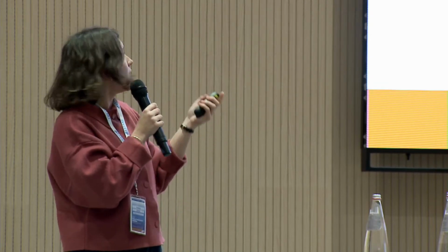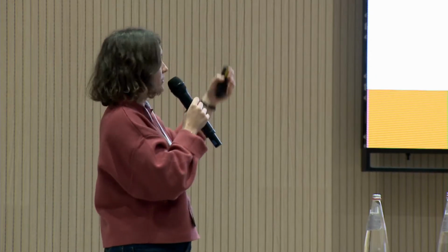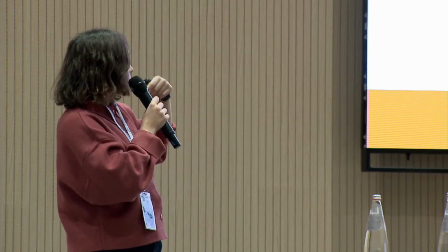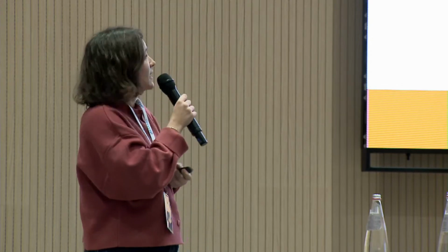And we formulated an optimization problem with the aim to reconstruct, in this case, flow values. So this is our minimization problem, in which the objective function is made of two different terms. The one circled in blue only takes into consideration the sampling and reconstruction, neglecting all the physical properties of water distribution networks, while the second part, circled in orange, ensures compliance with the physical laws that apply in those kinds of networks.